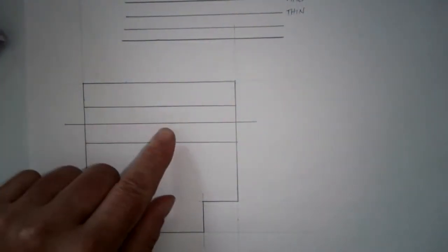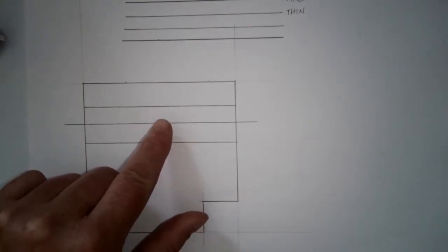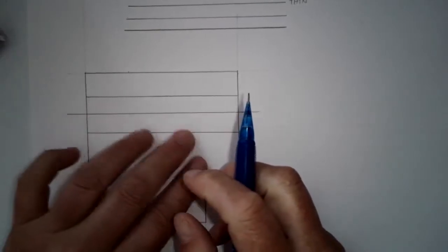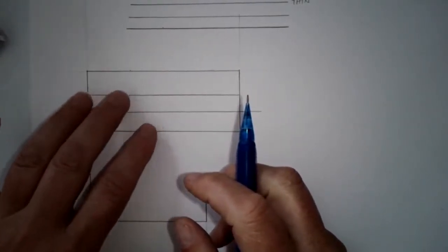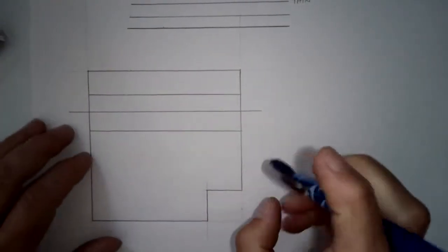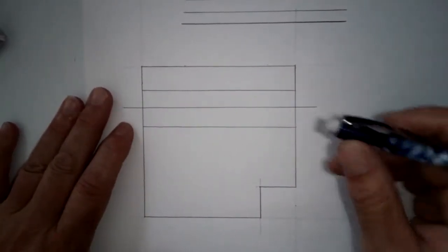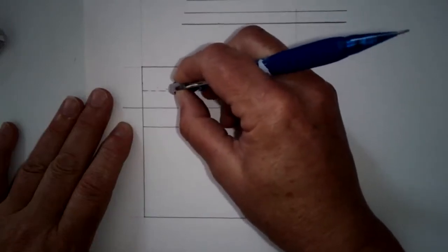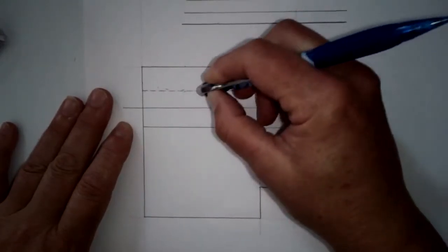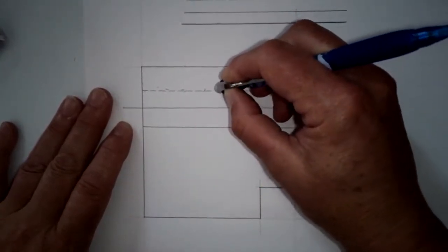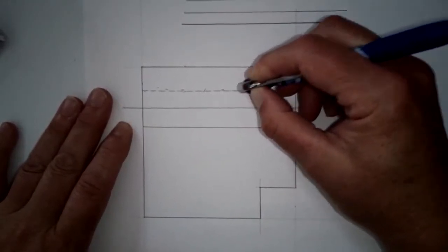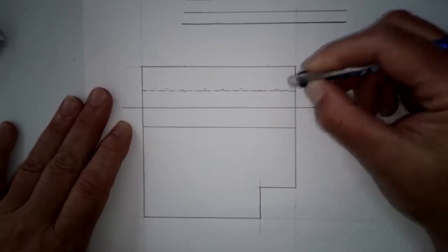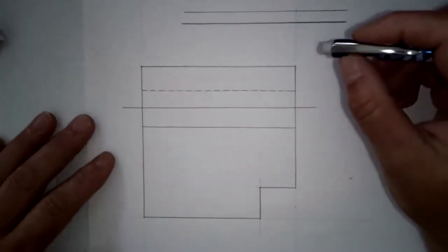And obviously I'd be a lot more careful about placing these lines. I'm kind of eyeballing things right now. Pretend that's in the center. But now this is going to be two hidden lines here, and this is going to be a center line. So to turn it into hidden lines like magic, we're going to use that eraser. And if you have an eraser shield with the dot pattern that goes across, this is a great tool to use to make sure that these hidden line segments are exactly the same distance apart.